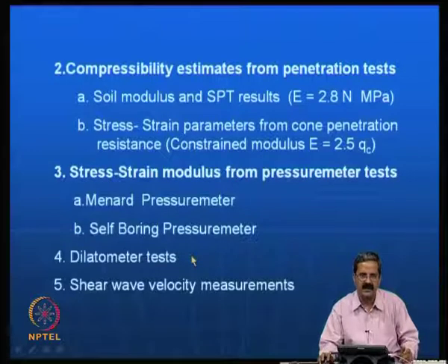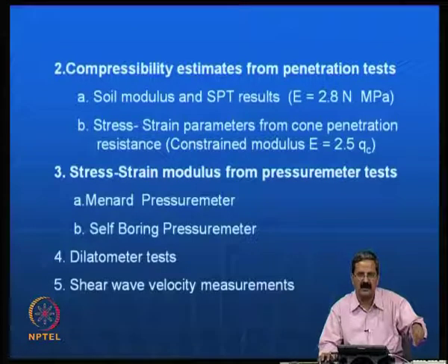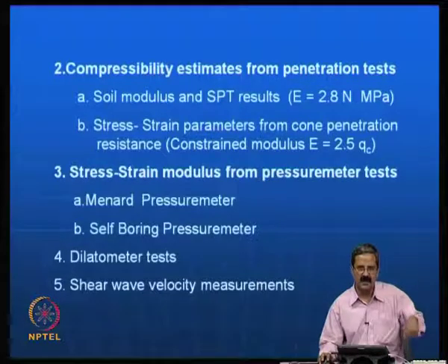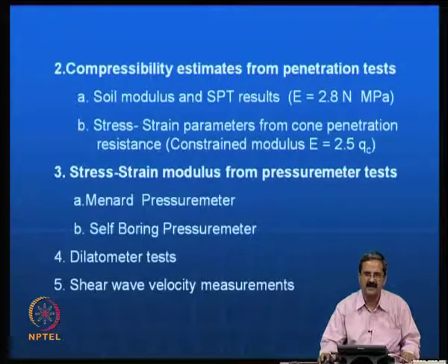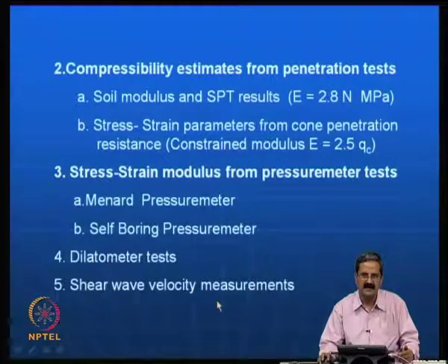The dilatometer test is a simple kit, and one can use it. Here again the principle is that you just put that instrument in a particular borehole and then you allow the diaphragm to expand, and resistance to deformation is measured. The diaphragm starts expanding because you apply some sort of pressure, and the pressure versus the deformation is recorded. You get a lot of information from both the tests, because the advantage is that you do not need to take undisturbed samples; you are getting the response of the soil from the undisturbed state itself. There are also some more measurements on shear wave velocities which are very popular, we will see some of them now.